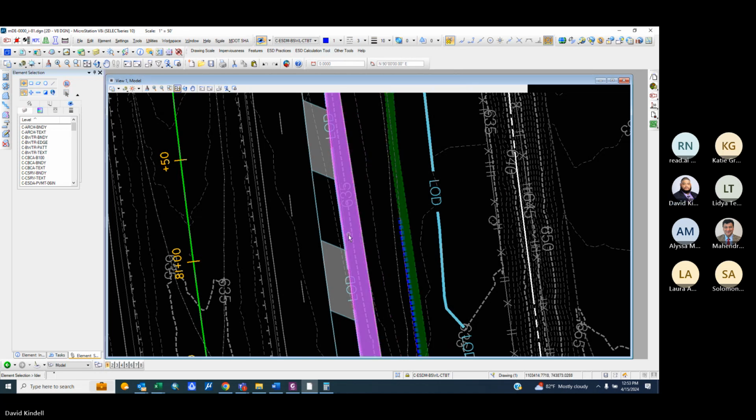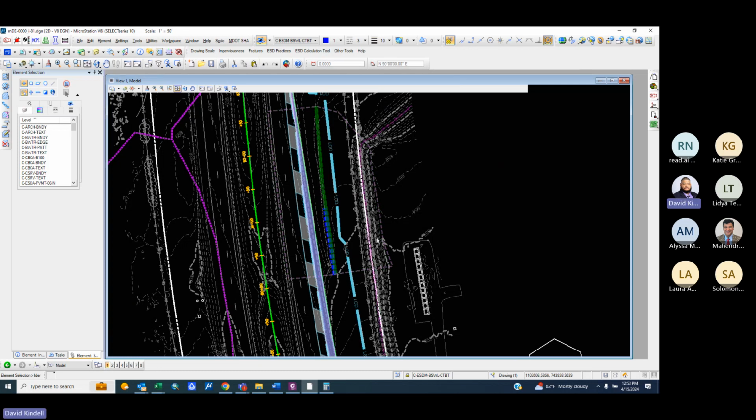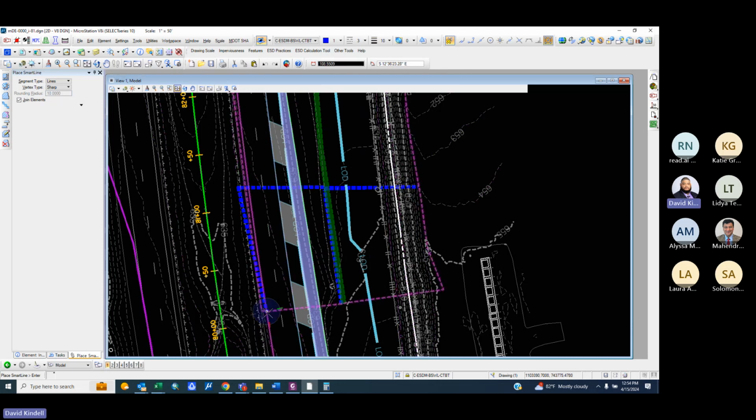That's going to be where the end of my swale is. But what happened to the drainage area? It'll be drastically smaller. And because your drainage area is smaller and the end of the swale is here, the impervious area treated becomes smaller as well. It will probably only be up to here.